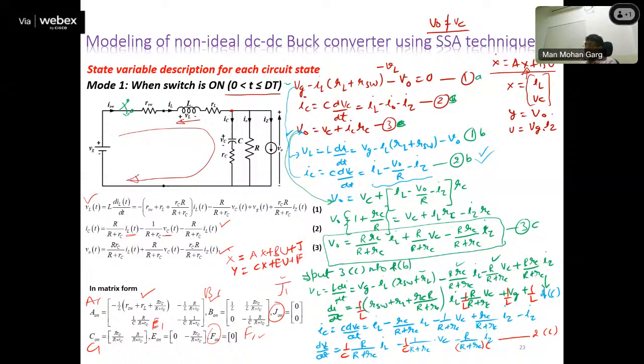And you will see when we take this into consideration, like in one of the classes, Professor Mishra told that when you model a battery, you take one voltage source and a resistance in series. The diode is there, and when the diode is on, we represent it with a voltage drop VF. So how do we represent that, because that VF is not a function of any U or anything? For that, these coefficients have been introduced. So our new model we represent in this way.